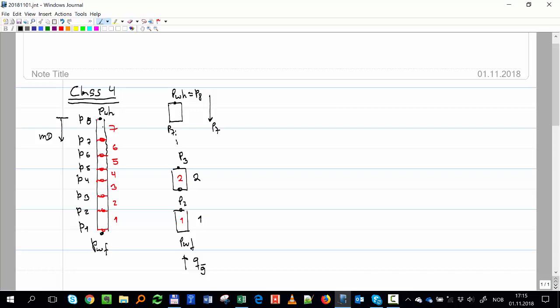However, each segment has something nice: they have the same standard condition rate. All the segments will have the same rate. So that's something that simplifies my life. Something that doesn't simplify it so much is that each segment has its own CT and S. This one will have CT2 and S2, CT1 and S1. Each one of them will have their own tubing constant, segment constant, and their own elevation coefficient. So that's part of the complexity.